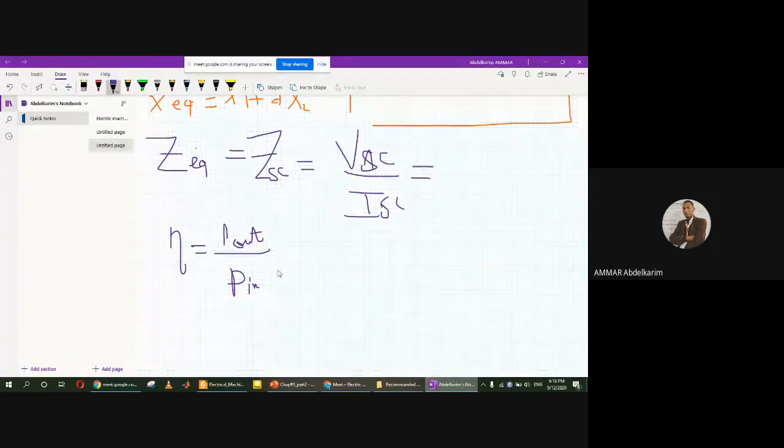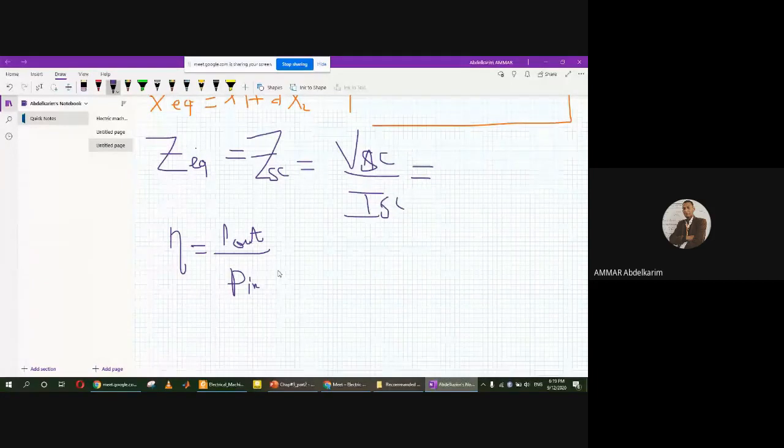This load depends on the characteristic of the transformer. For example, when we bring this transformer, we see the maximum of the current. For example, they said we cannot exceed, for example, 10 amps. So we cannot connect a load that consumes more than 10 amps to this transformer.